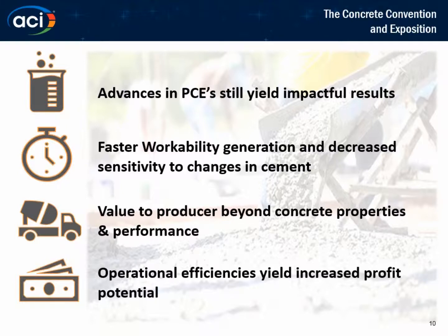So setting time, yes, there's no significant change in set time, so it's not accelerating the set of anything. The only acceleration is dispersibility, so you have rapid dispersion without rapid acceleration. I was more so concerned about retardation. Yeah, no, we are not seeing any retardation, any different. The setting characteristics and setting profile is the same as a general PCE.